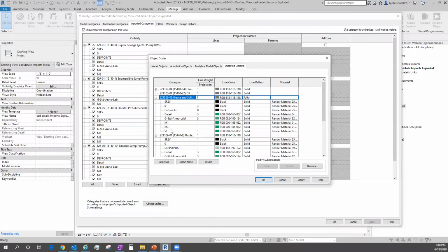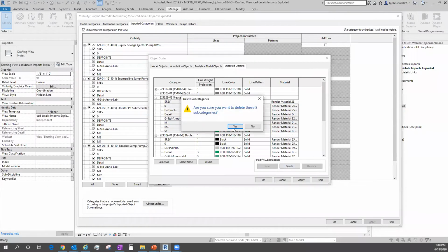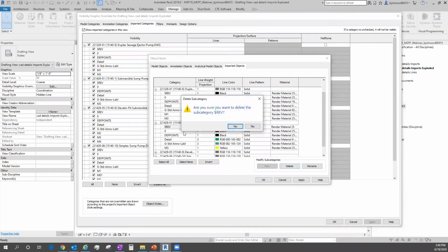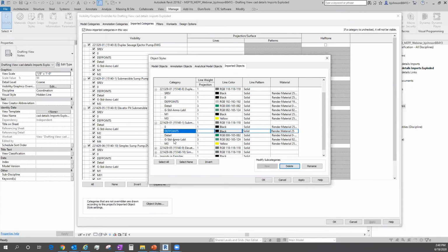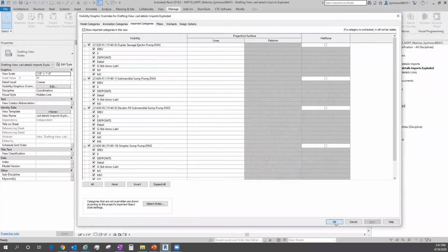When you do that, the things that are on the current layers will go to the last item above. So if I were to get rid of this rev and delete it and then grab these guys here, all these items that are on these 4 would go into layer 0 under there as I delete these. So you're not really getting rid of the objects that are in there. You're just getting rid of all the categories and the old layer names and moving them up in the list. So don't be afraid of that portion of it.